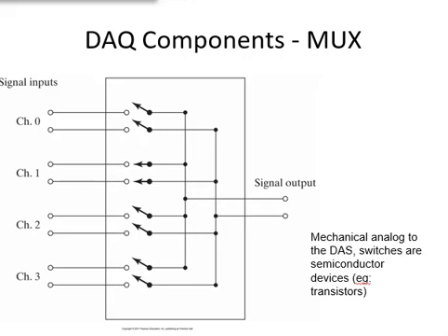Some channels may interfere with the channel being read. This error is normally a precision error. An additional error might occur if the output signal voltage is not exactly the same as the input. That is, the multiplexer alters the signal. The measure of these characteristics is known as transfer accuracy.